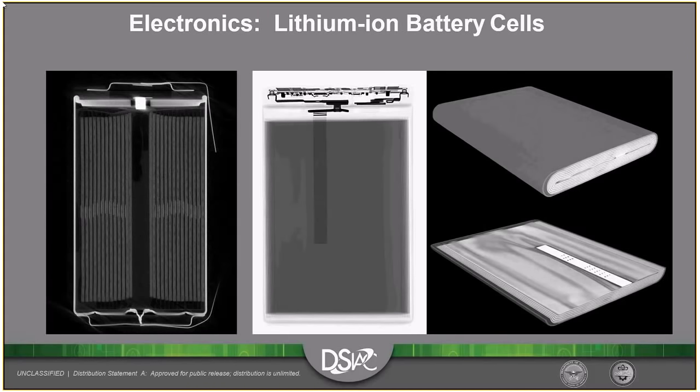These are pouch cells, so measuring that anode and cathode length in the corners is very crucial in the packaging. The Samsung batteries, everybody knows, those were catching on fire a few years ago, and that was due to the pouch cell here. The corners of the pouch cell were shrunk in, and the anode was rolling over on the cathode and essentially creating a short circuit.